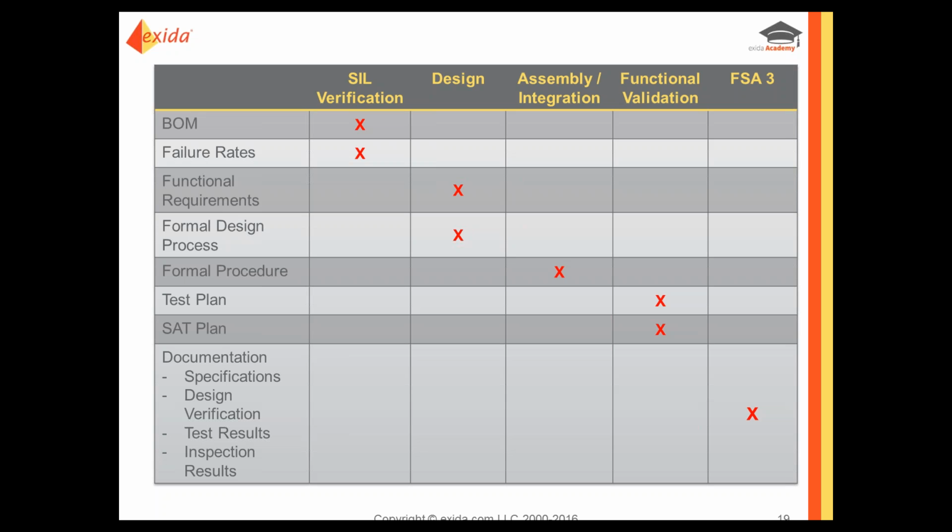Or, as I mentioned before, a hydraulic assist spring return actuator. It's common that it's designed so it just closes quicker, but if we don't have hydraulic supply, it's not safety critical. The spring will still close. So a failure modes and effects analysis is a good way to do that.